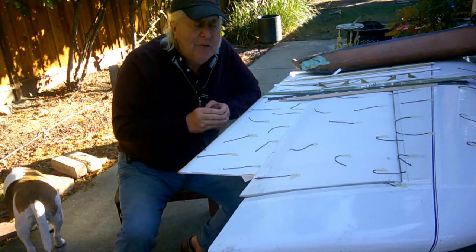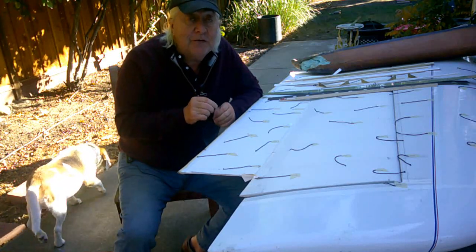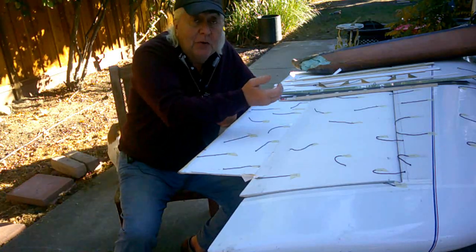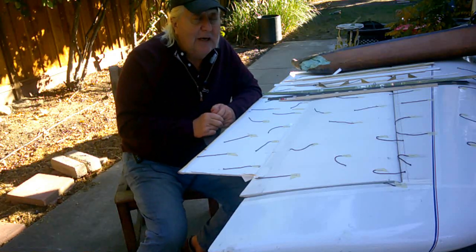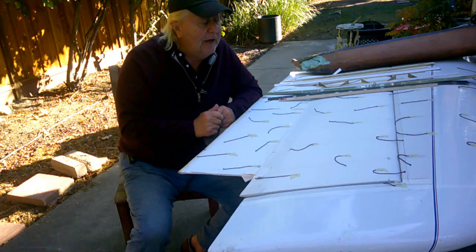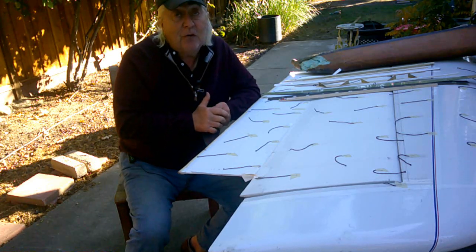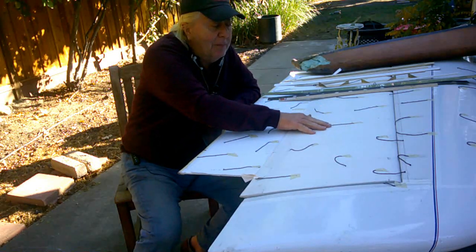Because physically we can't see the flow on the wing. If you have very controlled conditions and a smoke flow injector and all that, you might be able to see the boundary layer. Very specialized equipment, you can measure the boundary layer. But of course we have nothing like that here. And the tufts don't tell you anything about boundary layer.